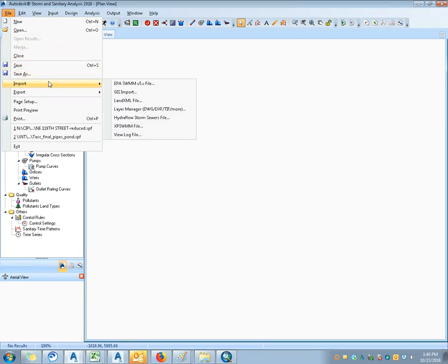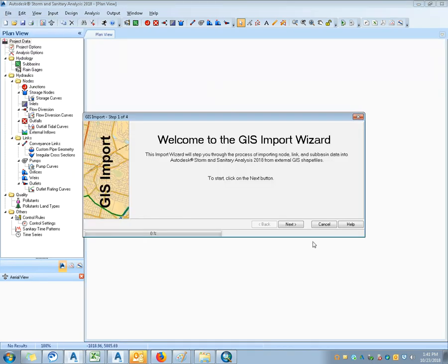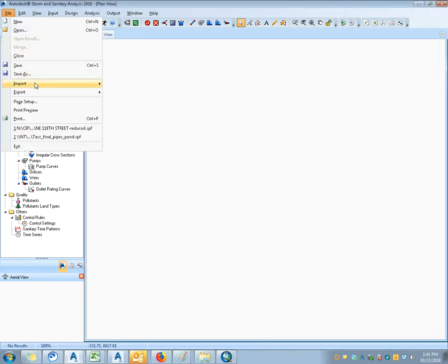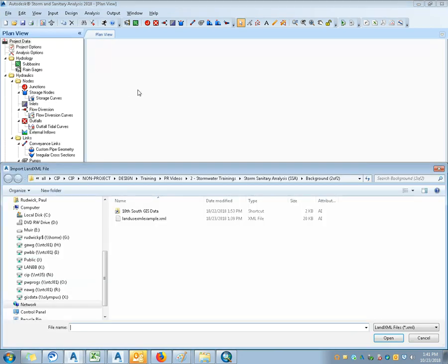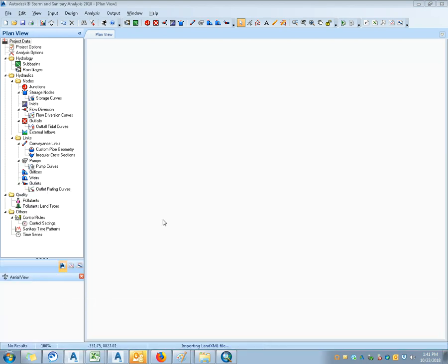Plus, Paul, doesn't it have some geographic sense? Like if you change a boundary on a parcel that's adjacent to another parcel, it maintains single borders and things like that. Totally. As well as the Civil 3D intelligence. Yeah, you're right. It does all that stuff. Really what they're meant for is land divisions, they're called parcels, which gives you a little sense of what they're supposed to be used for.